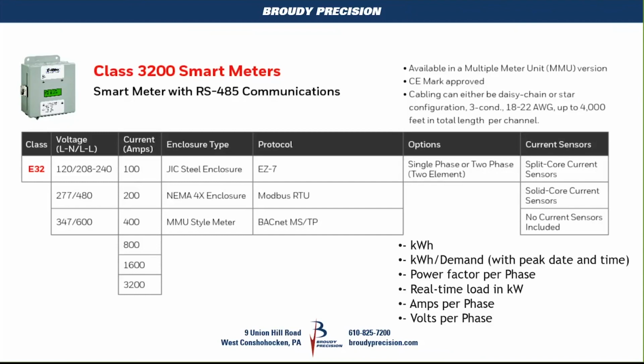I know it was in the past, but it may have been phased out when Honeywell purchased E-Mon. But certainly Modbus RTU, which is the 485 communication, or the BACnet MSTP. And this would integrate to our Niagara-based control system.